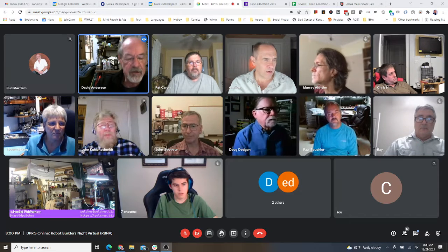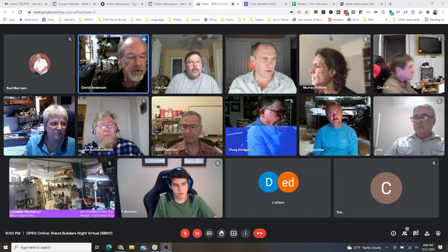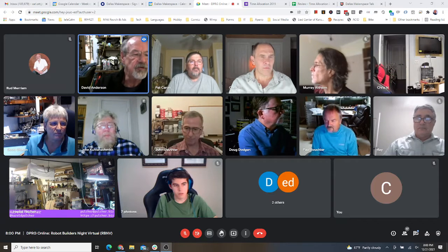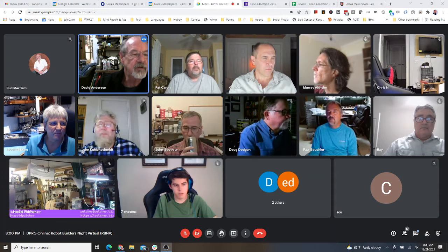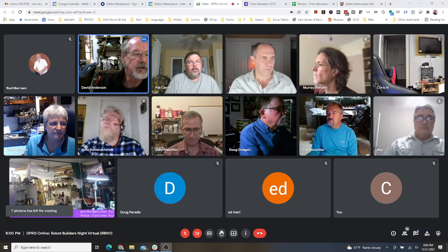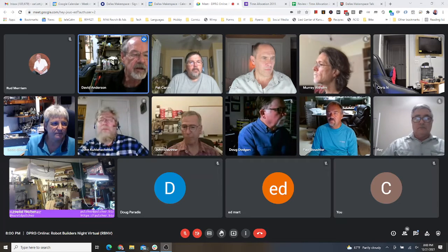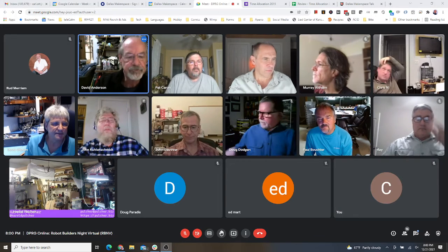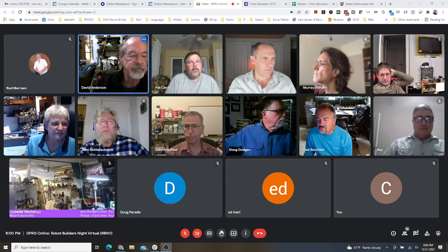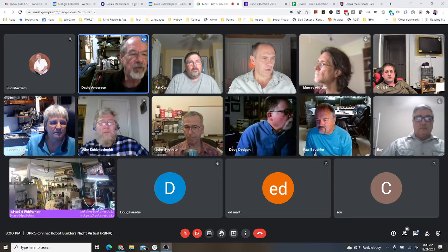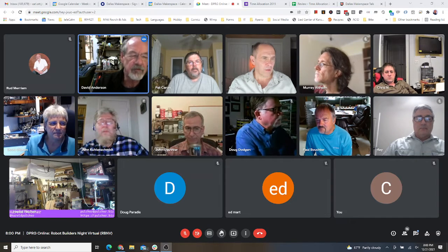I do have some code. I think I showed a video of it here where you can give the robot some landmarks, basically just corners where it can go and measure the distance to the walls and not only correct its location, but correct whatever drift there's been in odometry. I'm sorry, in theta, in heading. And really, if you can correct drift in heading, like using SLAM or something like what Chris is doing with RAWs, then pretty much the other errors go away. They're still there, but they're not significant. But the errors in heading are very significant because they throw everything else off.